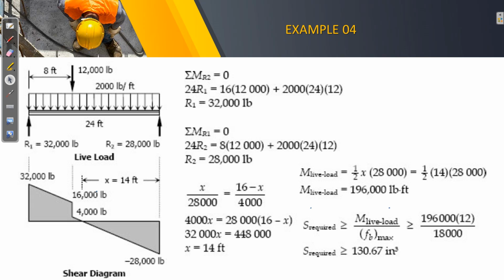So the first thing to do is to establish your shear diagram. Anyway, shear diagram will just give you the shape that will be your basis in the ordinates of the maximum bending force. So of course, your beam is no longer symmetrically loaded.